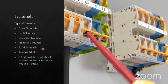Then there are terminal blocks. Terminal blocks are nothing but just a bunch of blocks of terminals. You can always connect one single wire and then distribute to the other ends of the terminal throughout the panel. So you don't need to connect every wire to every terminal. If you have a 24-volt distribution supply, like there are 10 instruments that will need 24-volt inside the panel, then you just connect one 24-volt to this terminal block, and then you can get 10 outputs from these distributed blocks. So that is terminal blocks.